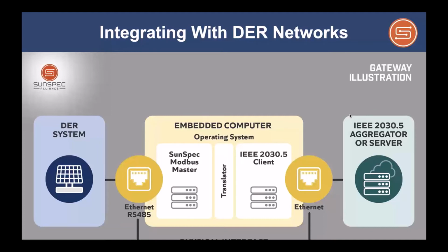And so here's the classic example and environment that is present in California, where California requires IEEE 2030.5 for utility, a network operator to system communication. Now, of course, that's all going to be done over the 2030.5 network. Once you get to the local system, what you're going to encounter quite often will be SunSpec and SunSpec Modbus. And so ensuring that we have this semantic identical behavior and compatibility is the key trick.